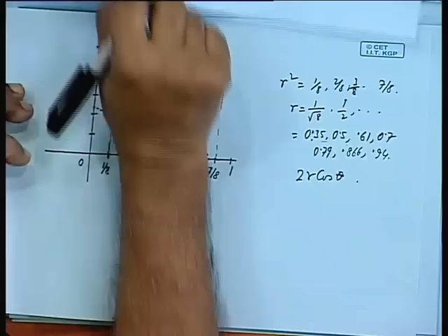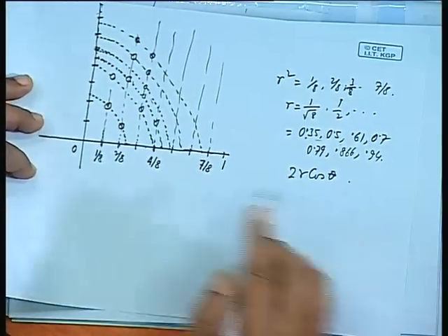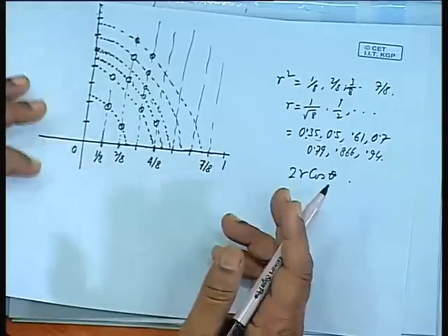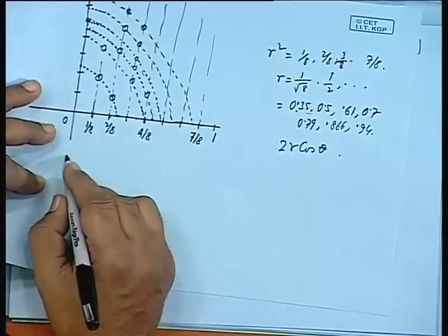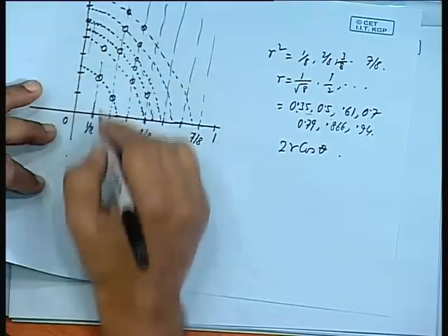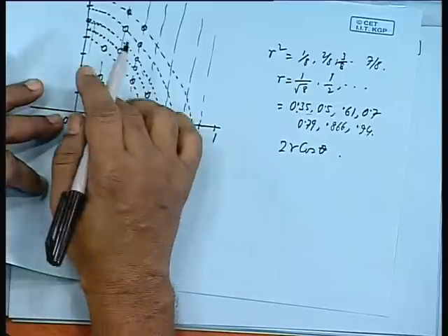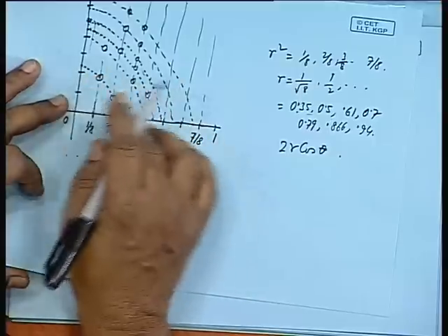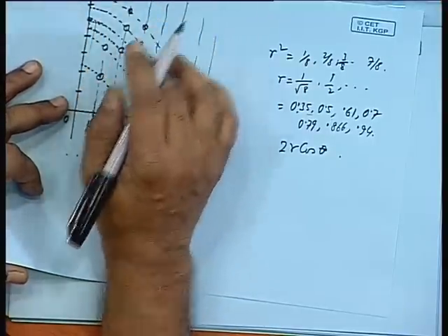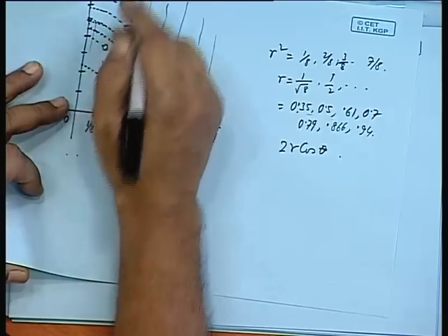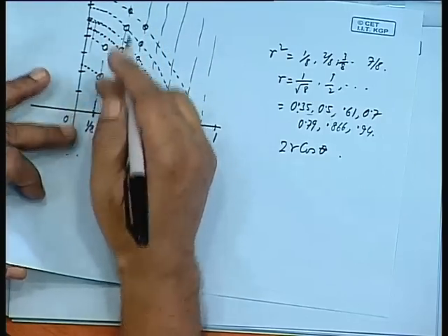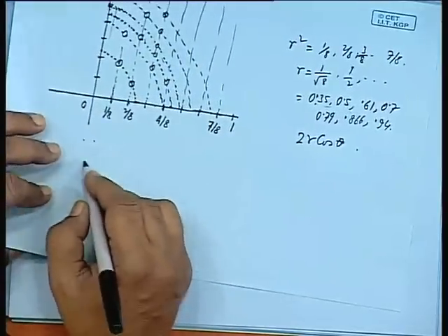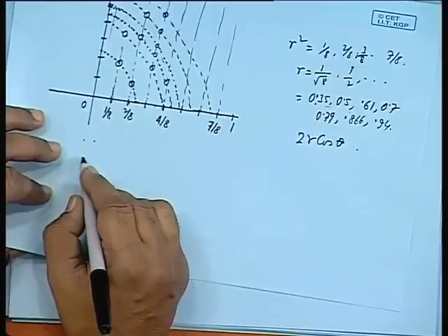If you increase the bit representation, that is, instead of 2 to the power 3, if I have 2 to the power 4 or 2 to the power 5, 2 to the power 6, if it is an 8 bit number, then this will be partitioned much more closely, and hence the distribution will appear more or less uniform. It will still be a little rarefied on the lower side and a little compressed on the higher side, but you get more discrete values, and the discretization will be very close. There is another representation of the same quadratic form. This is very interesting.